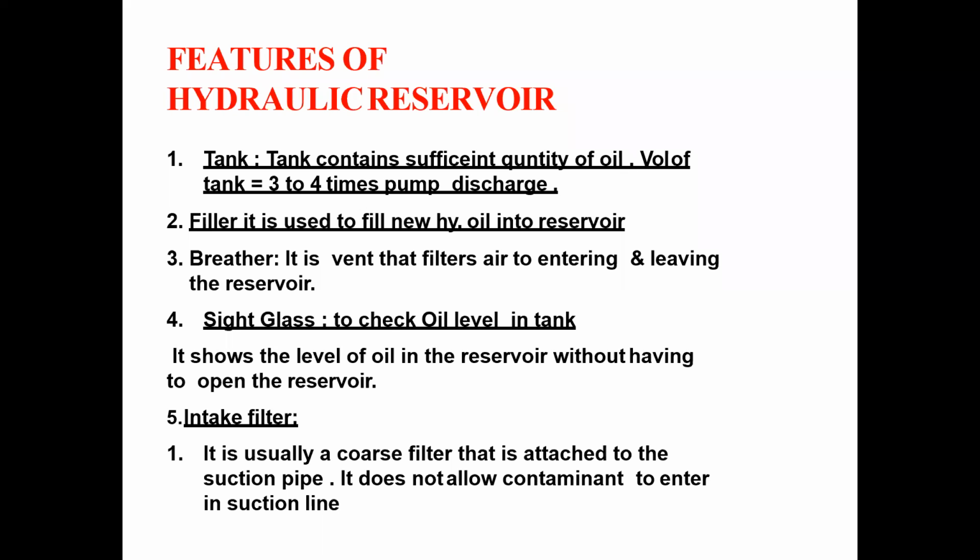Filler is used to fill the new hydraulic oil into the reservoir. If you observe the reservoir, there is a single outlet provided where you are going to fill the new hydraulic oil, and this component is known as the filler. Then breather, it is the vent that filters air entering and leaving the reservoir. As in the previous slide we discussed the air vent, the breather is used to avoid the creation of vacuum in the reservoir.